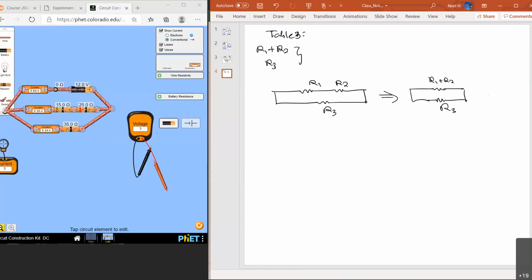Because of that, the effective resistance, or the R equivalent, is going to be equal to (1 over R3 plus 1 over (R1 plus R2)) to the negative power 1. Okay, make sense? Good, any question? So you have to do the effective resistance this way for the new circuit.